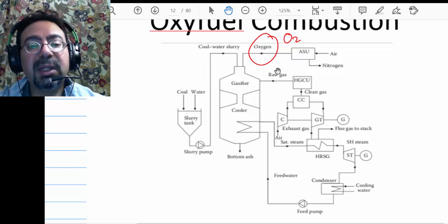And you can see how he's basically doing a combined cycle over here too, right? So the raw gases are run to a combustion chamber, and that combustion chamber is using air to burn, and a gas turbine. The exhaust of the gas turbine, before throwing it away, he sends into a steam power plant. Okay, and the steam power plant is fired by that exhaust, and also a little bit the water over here is being preheated by the furnace of the coal.